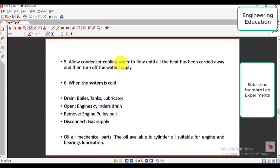Allow condenser cooling water to flow until all the heat has been carried away, and then turn off the water supply. When the system is cold, drain the boiler tank's lubricator, open the engine cylinder's drain, remove the engine pulley belt, and disconnect the gas supply. Oil all mechanical parts. The oil available is cylinder oil suitable for engine and bearings lubrication.